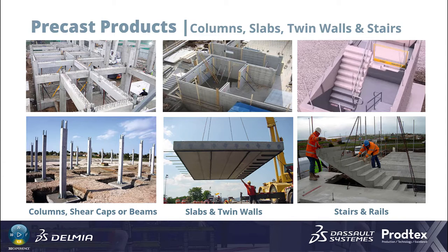At the core, you'd probably have that top slab finished, but throughout the rest of the building, you might use a slab with exposed rebar and do the final pour in the field, so you're reducing the weight for transportation.